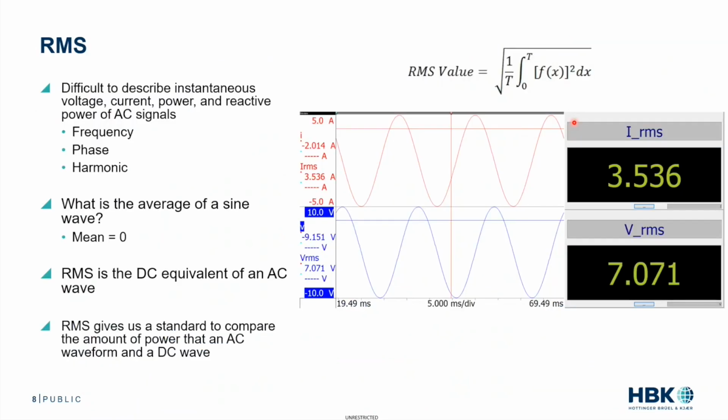So that brings us to RMS, which one of the topics today is why are my RMS values different instrument to instrument? And what it ends up being is filter to filter. I'm not going to ruin any surprises. But the RMS is really, we take a sinusoidal signal, and rather than describing it with frequency, amplitude, wave shape, we can simply describe it as the root mean square. So the root mean square, if we take an average of a sine wave, it comes to zero.